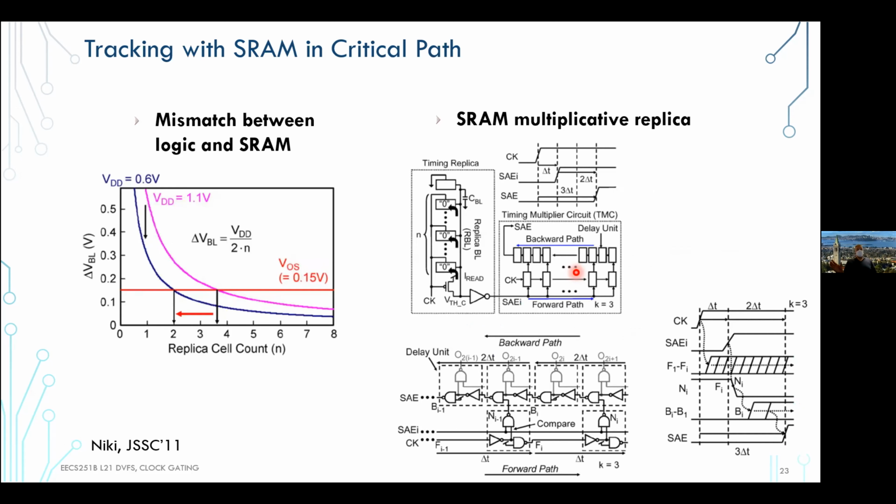It's a little bit of a different story on the SRAM side, because you have bit line discharge, you're activating a long capacitance word line. So it's kind of like different types of circuits driving different types of capacitances. And versus voltage, it ends up being hard to track those timings. When should your sense amp fire? When has enough voltage been developed for a given